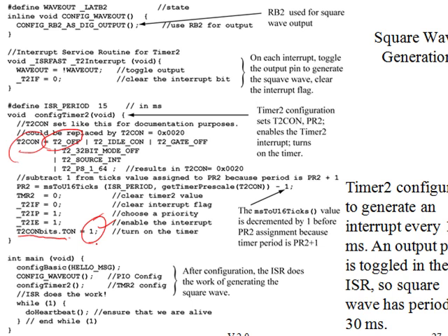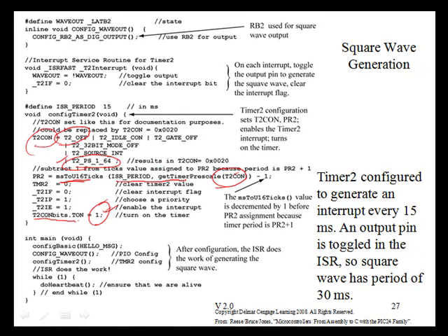So now the timer is now counting after this line is executed. One thing about this particular library function, since it's reading the timer prescale value out of the timer 2 configuration register, you need to write the timer 2 prescale value before you actually call this function and pass in the configuration register value. Let's look at what's happening in our main.